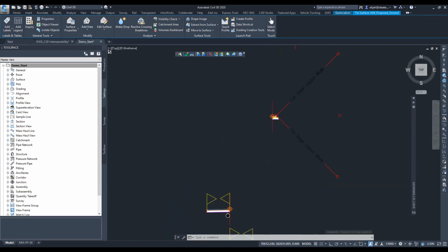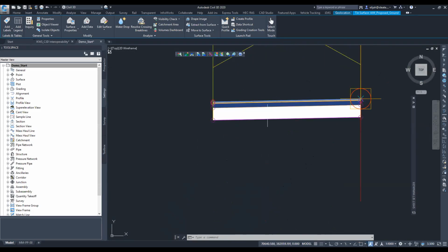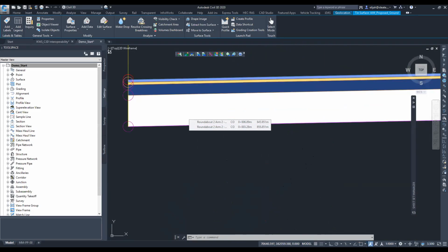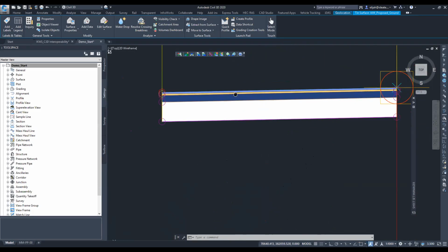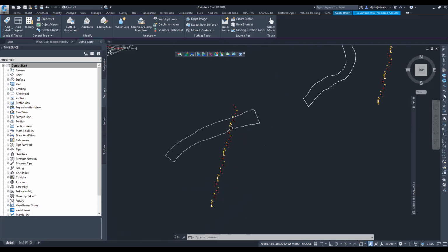So your work now is only to ensure that the various camber or slopes for those assemblies are as required, and the minimum thicknesses of the road assembly that you want to use, like maybe the riding surface for the road should be 20 millimeters bitumen, or maybe the base should be 300 millimeters. So each of those are what you now need to ensure meet the requirement as per the definition by the materials engineer.